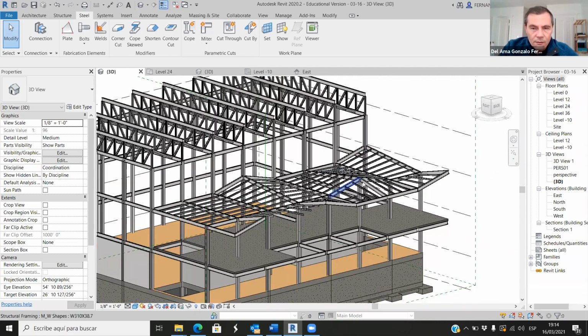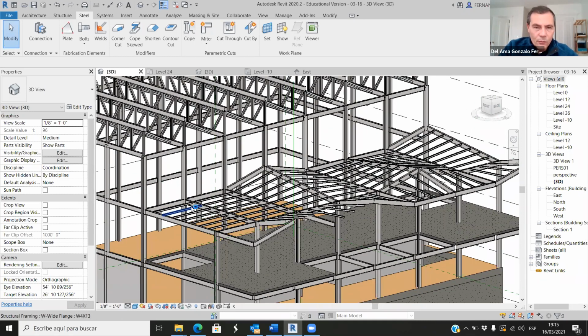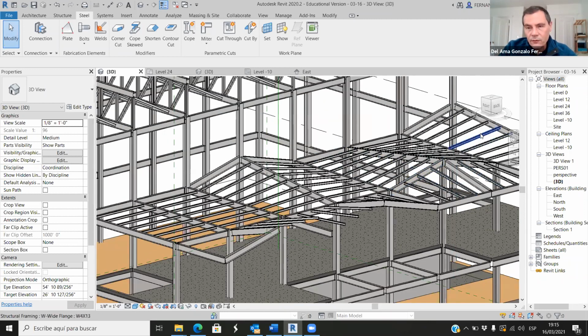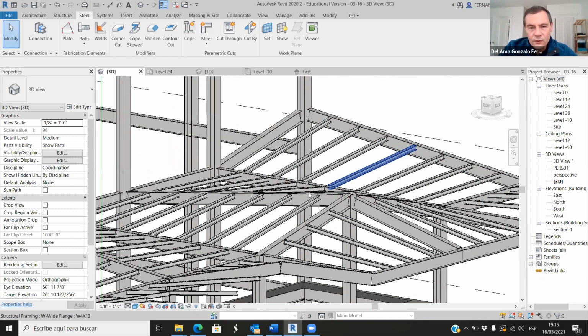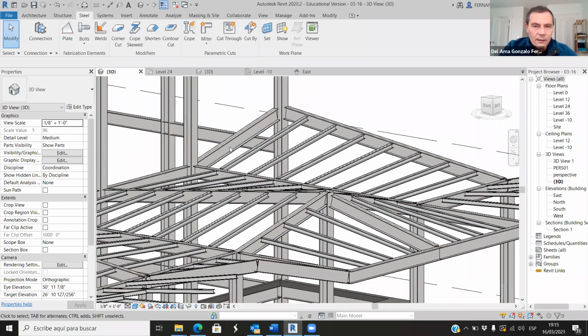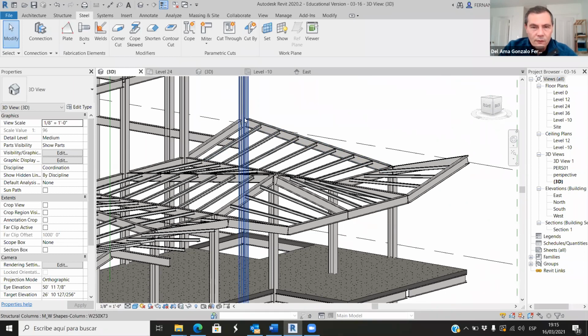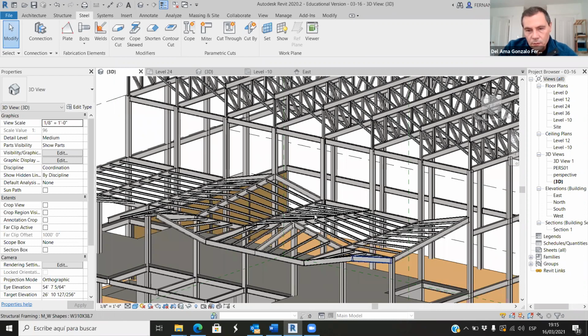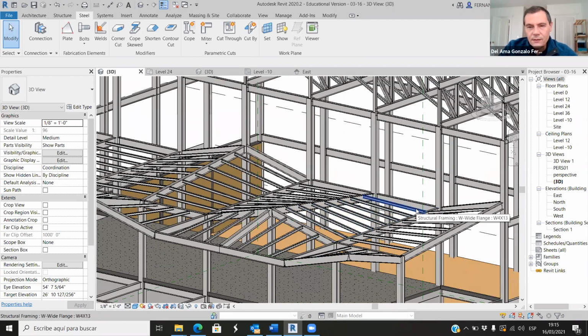So when you are doing this, you can do whatever you feel like. I mean, you can use the same pattern I'm using, or you can use a different one. But if I analyze this from the water perspective, this cannot happen. Okay, so there can't be slopes towards the building itself. Imagine that you have a drop of water here. What does this drop of water do? It goes that way. Okay, that's fine. But if it goes towards the building, this is wrong. So it cannot happen.